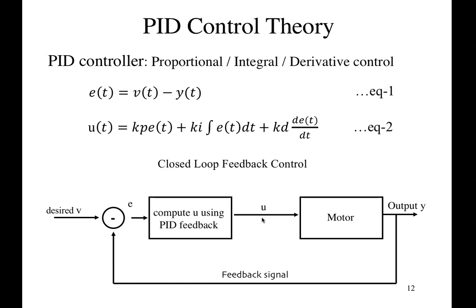And because it reacts instantly, anytime the error goes up, the control output goes up. Anytime the control error comes down, the control output goes down, and it is in a proportional relationship. So that's why it's called the proportional term. Kp, remember here, is a gain we select as a control engineer, or we tune sometimes online.